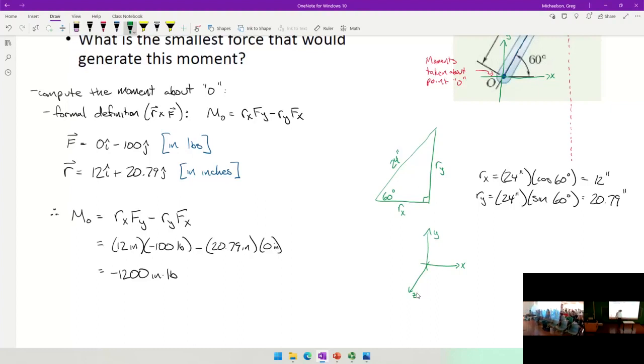So this is the x-axis, this is the y-axis, the z-axis is this way. I'm going to take my thumb and point it towards the z-axis. Now the way that my fingers are curling indicates positive bending moment, positive moment. So I would say that based on this, positive moment looks like this, right? In which case positive moment is, was that counterclockwise?